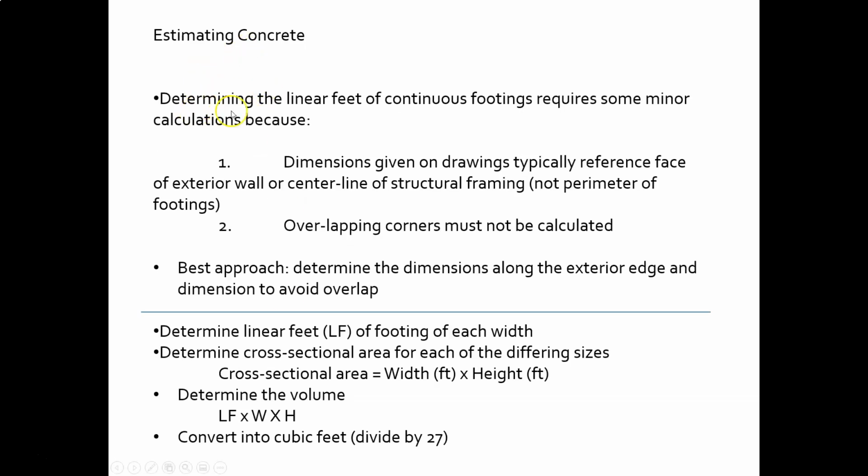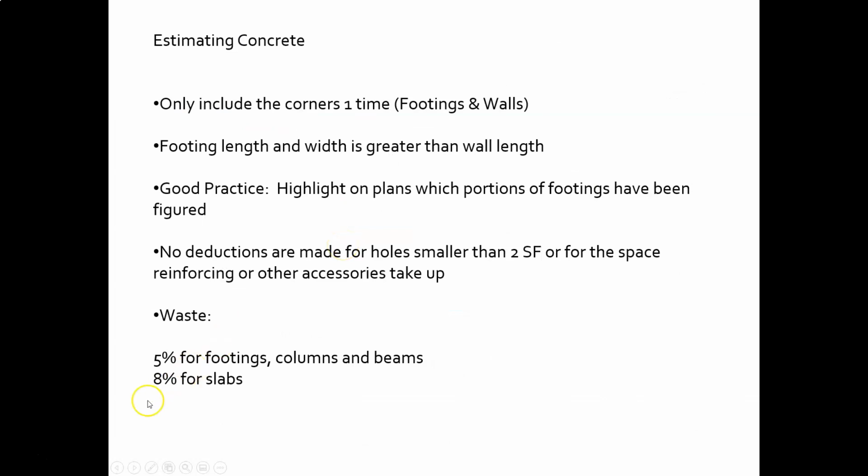Okay, let's keep moving. Just to follow up on that point, this is a number you would adjust per your experience. This is not set in stone. Set in concrete, so to speak. No pun intended. If your experience shows that you're not wasting all this, then don't add it. Don't buy more concrete. Don't drive up the cost of the bid. So don't just accept these numbers. The best way to come up with this number is by your own historic practice, paying attention to the amount that your crew is actually wasting.